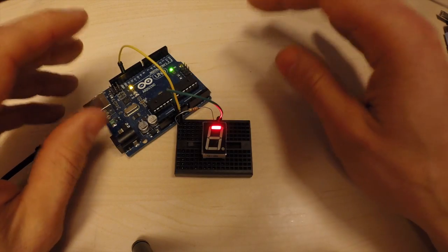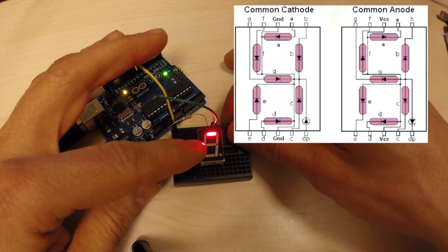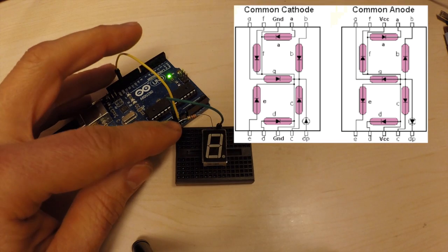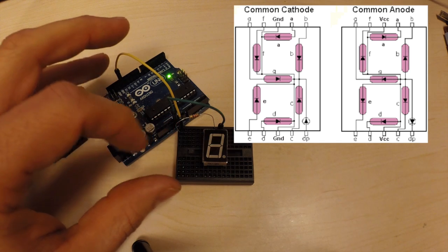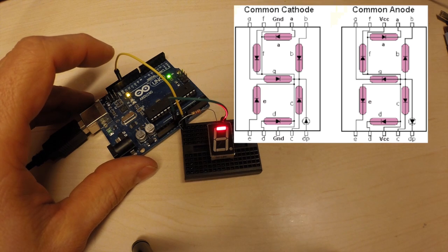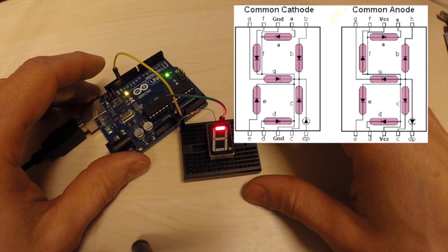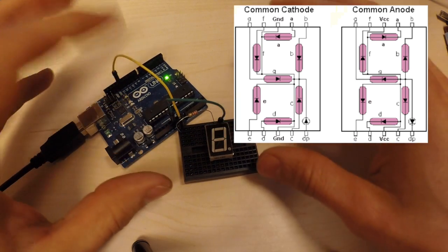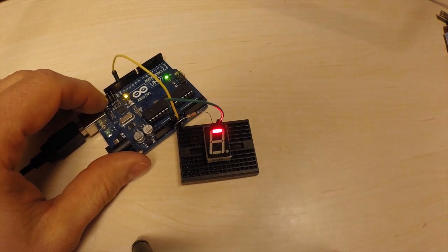One important thing to think about when ordering your 7-segment LED displays is if you want to have a common cathode or a common anode. This makes a huge difference, especially when you start using the shift registers and the special LED drivers like the 4511. You need a lot of extra components, as I will show you in the next episode, or you'll need to totally change the code for the shift registers.